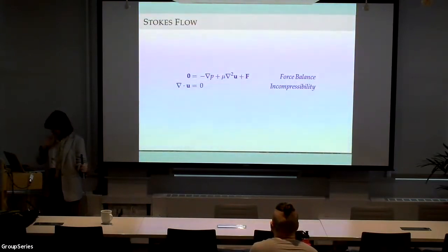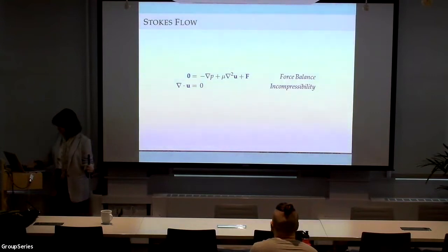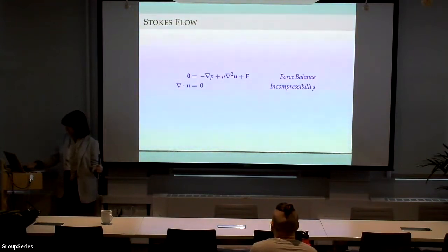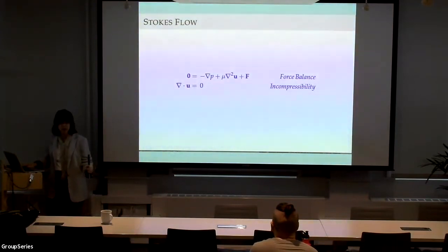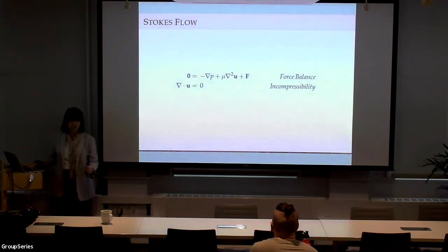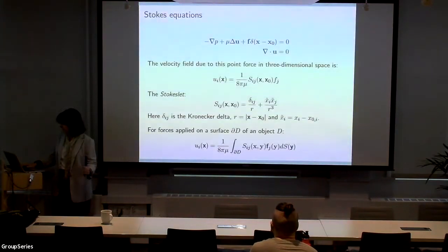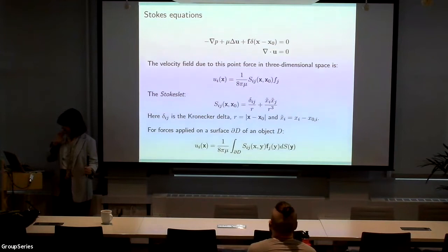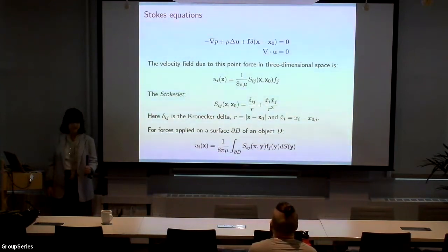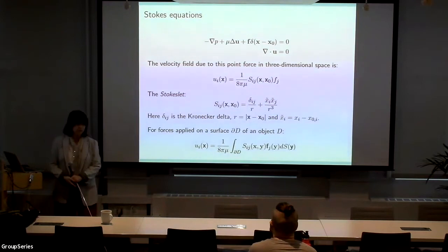And so when we non-dimensionalize and take, for instance, the Reynolds number going to 0, we get the Stokes equation. And I like to think about the Stokes equations, and I like to think about what makes them so odd. So here, when we take the Reynolds number equals to 0, we have no time appearing explicitly any longer. At every moment, the system is in equilibrium. All of the forces balance. The beautiful thing that we all know is that we have fundamental solutions.